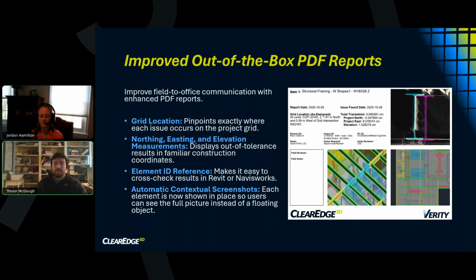Another key one is the element IDs. So we got the Revit ID, the Navisworks ID, and the IFC GUID information. That is now all included in the report if those ID informations are present in the host element. The reason we did that is because that allows users to very quickly go through, take that element ID information, and basically that way they can track down the element in the host application.